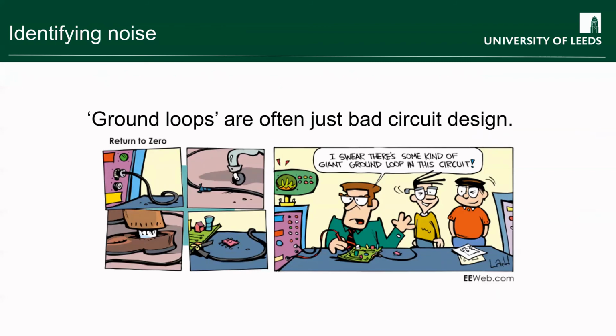The other thing to say, of course, is that it doesn't matter how good you are at identifying the source. If your actual experiment is not well designed and not securely built, then you're going to have problems no matter what. And again, nearly always the problems end up in cabling. If you have a problem, before you start thinking that your meters or your hardware are broken, you want to first check that the cables are good, because the cables are always the vulnerable part of an experiment. The cables flex, so they tend to break connectors. They're liable to be pulled around. They're liable to be laid out in ways that aren't great. And in extreme cases, they get stood on and broken. It's very bad for cables if they get put in too tight a bend, because you tend to break the insulation, or worse, break the conductors.